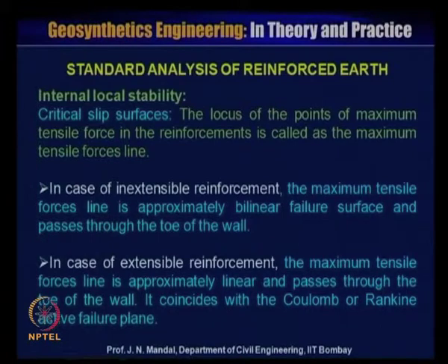Now, I will discuss some standard analysis of reinforced earth. This is the current reinforced earth system analysis, the internal stability. Now, we should know what is critical slip surface. Critical slip surface can be defined as the locus of the point of maximum tensile force in the reinforcement, which is called the maximum tensile force line.